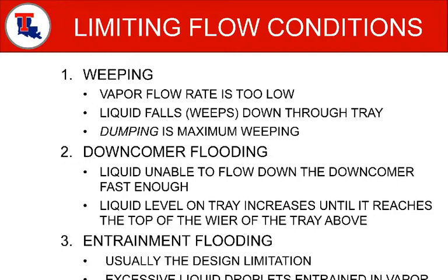This is a very practical question. Increase the temperature. Increase the temperature how? Reboiler or steam. Good, very good. So inject more steam, or try to increase the power, BTU, you are putting into the reboiler. Then comes the extreme condition, where instead of just liquid dripping through the trays, it's actually pouring. That's called dumping. That's excessive weeping.